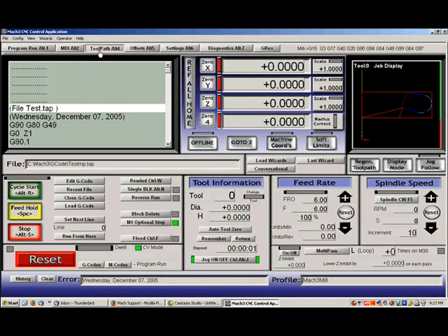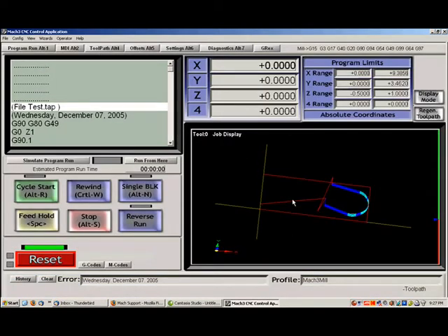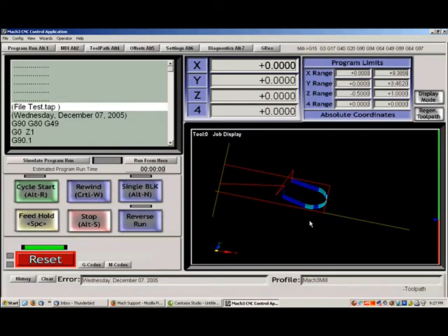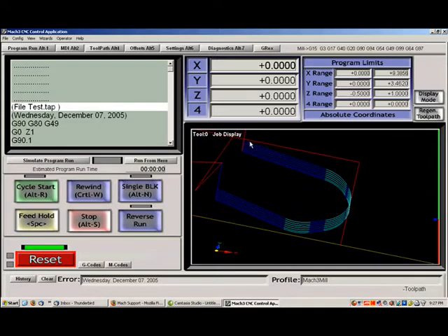We're going to go into the Toolpath display to view this a little more closely. And you'll be able to see that it took 75 thousandths per pass until it reached the last pass, where it couldn't quite reach it because it reached the half-inch depth of pass before it reached the 3/4. And all the in-feed moves were done at the same place, so it just repeated the file to get to the right depth.